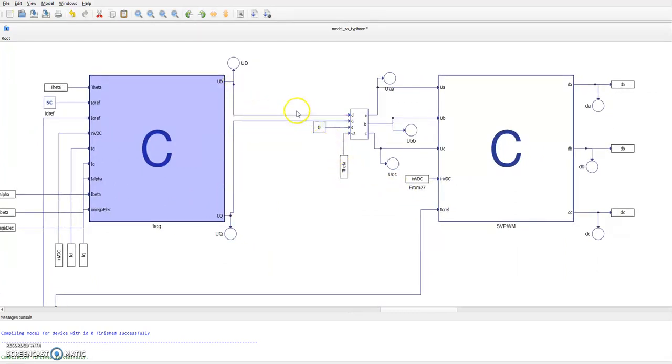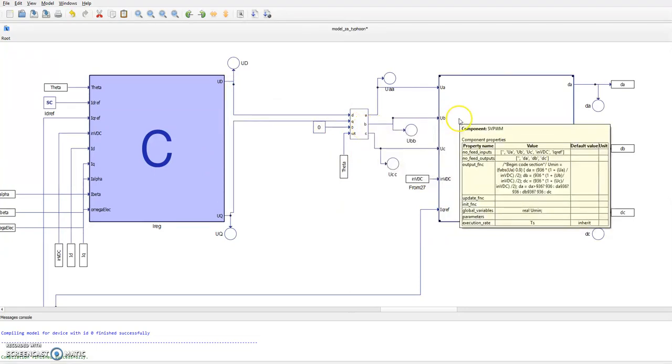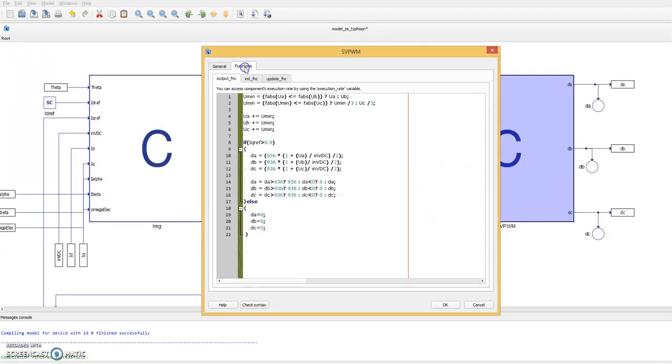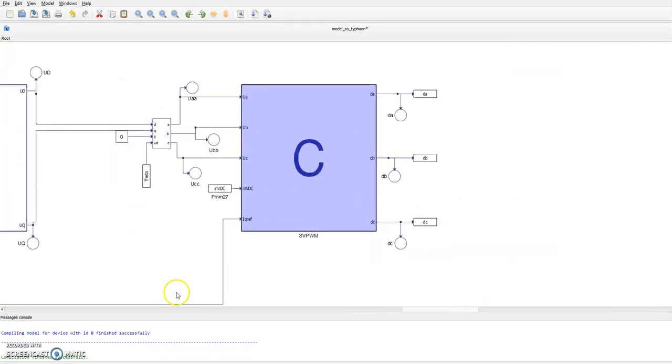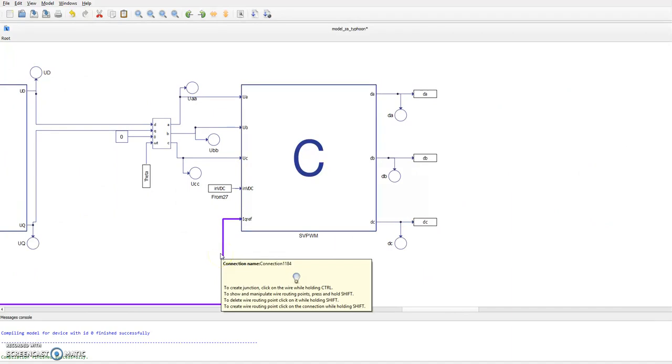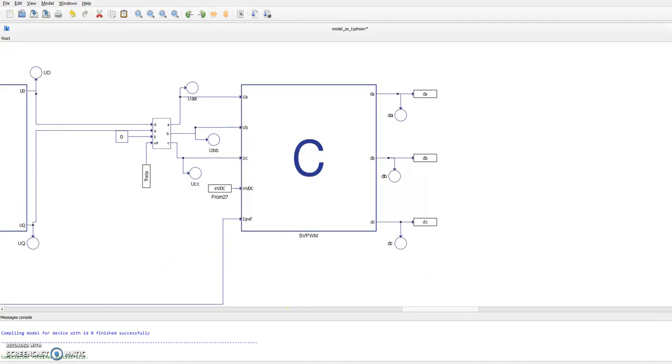Those voltages are transferred from alpha beta to the ABC system right here, and the space vector modulation block takes the minimal of all three, sums up with the inputs, and gives out the duty cycle references to be used as a control for the transistors. Let's now move on to the SCADA system.